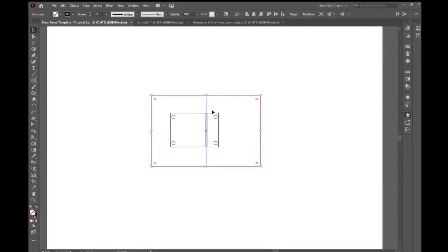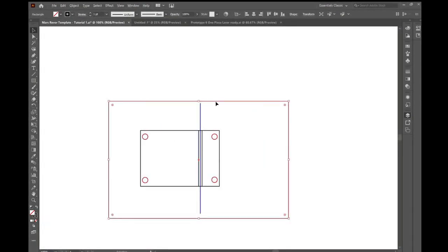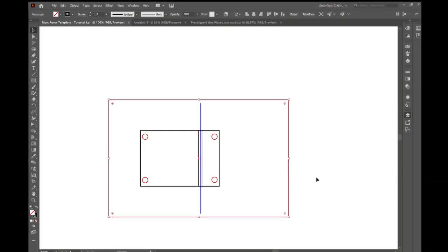You then need to locate the square so that it lines up and intersects that shaft for your gearbox in both horizontal and vertical locations. There we go. So the center of that box is now lining up to the center of that shaft. That'll make sure that when we put the pulleys on, the tension is correct on both the wheels.